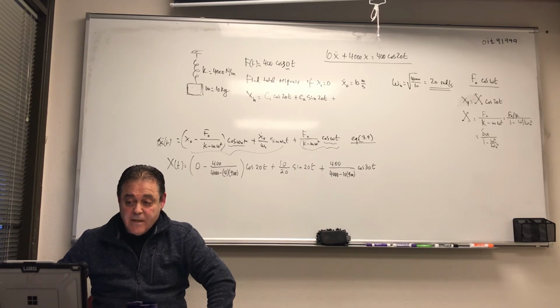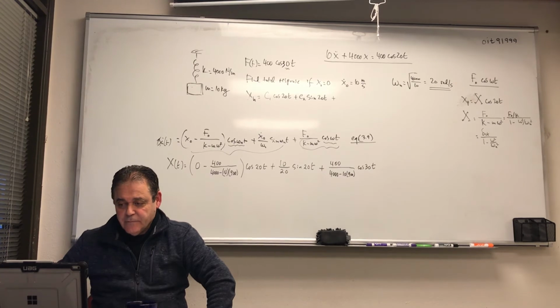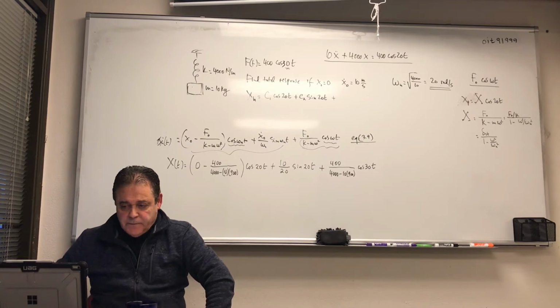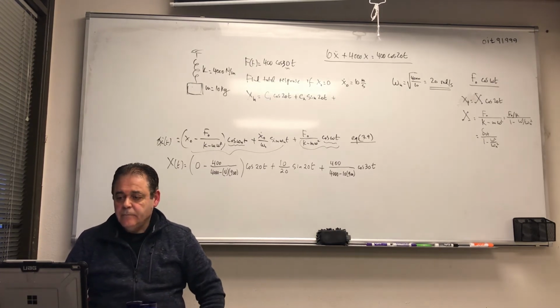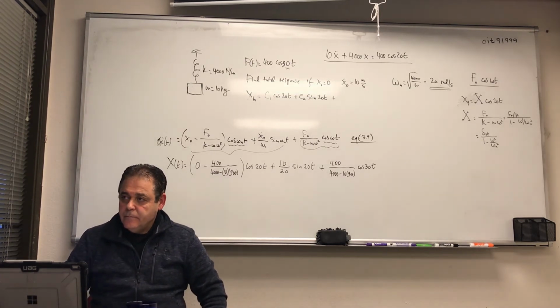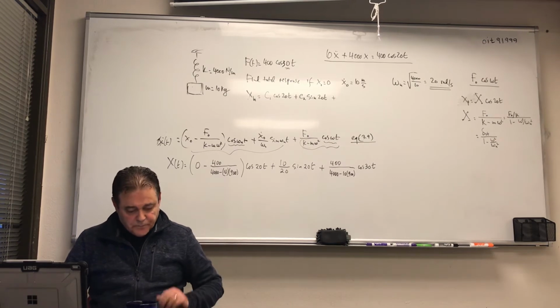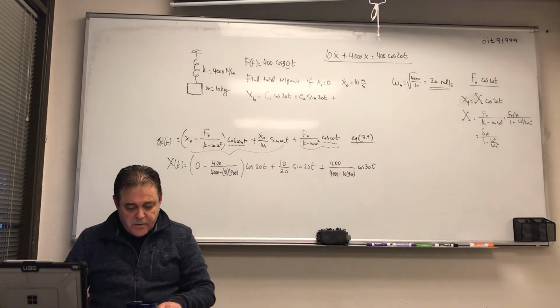So what is the problem? A spring mass system consists of a mass weighing 100 newtons with a spring stiffness of 2,000. The mass is subjected to a harmonic force of 25 at resonance, so omega equals omega n. Find the amplitude of forced motion at the end of a certain number of cycles.